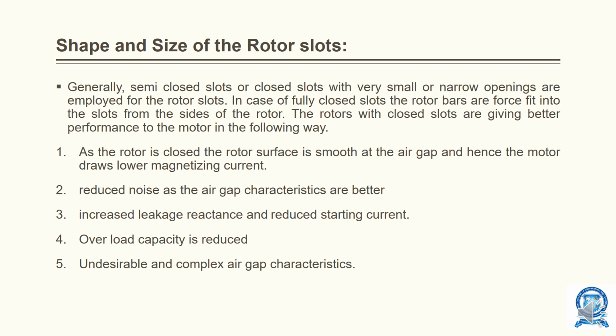As the rotor is closed, the rotor surface is smooth at the air gap and hence the motor draws lower magnetizing current. Reduced noise as the air gap characteristics are better. Increased leakage reactance and reduced starting current. Overload capacity is reduced, and undesirable and complex air gap characteristics.